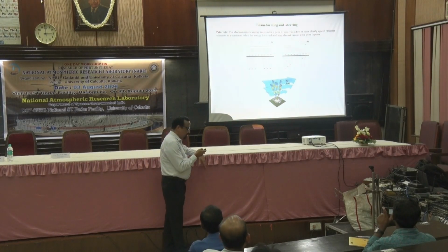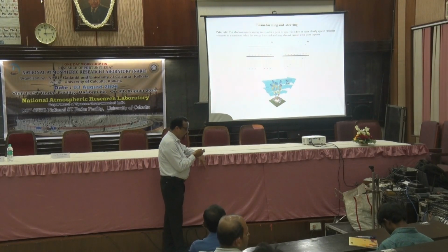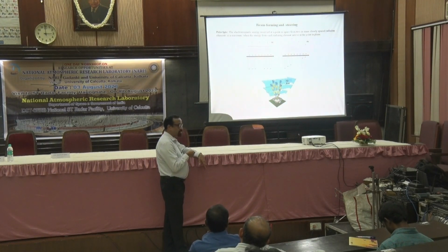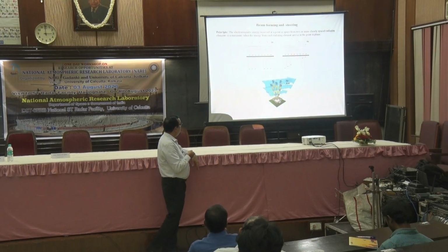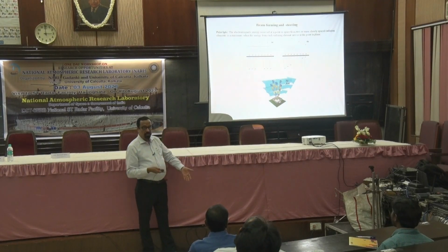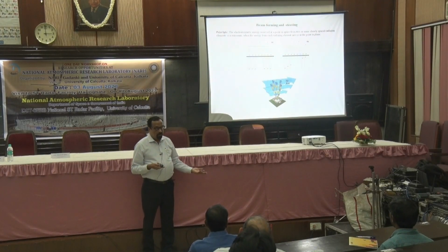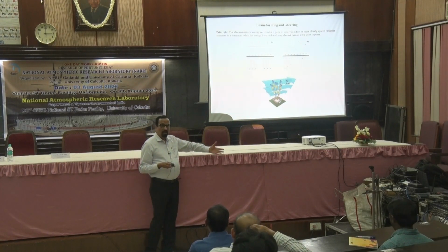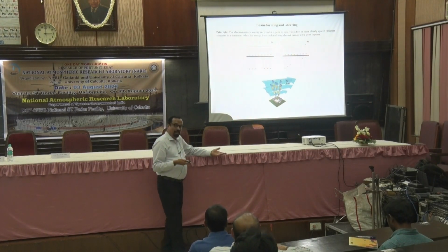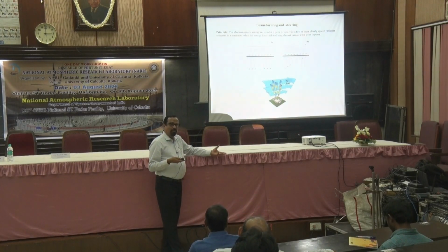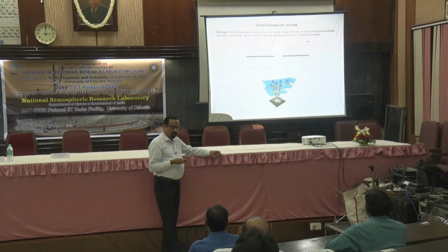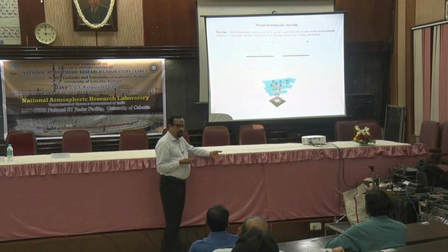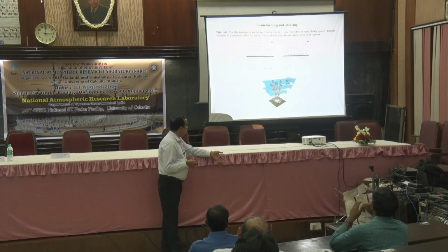As he was explaining, when you are forming the beams, normally what you do is phase shifting. Each one goes through different phases and finally you sum them up on one side and make a planar wave. That is the simple principle of beamforming. So here also, in principle, different phase shifters are used in the hardware, or in the new generation system each line can have its own DDS, or direct digital synthesizer, which generates its frequency component with a phase shift independently, without needing hardware for it. That is what new technology talks about, but it is a costly business. You can still do that.